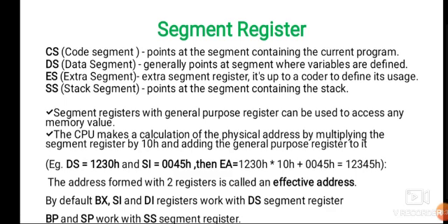The data segment will point to where the variables are defined. Extra segment is an alternative data segment; it does the same thing as the data segment register. Stack segment will point to the segment containing the stack. These segment registers can be used to access any memory value.